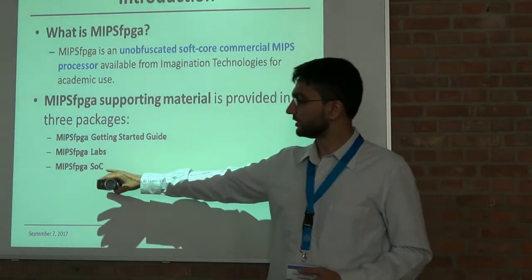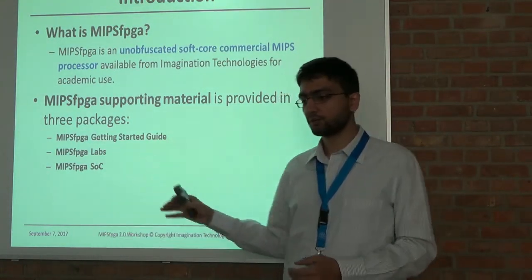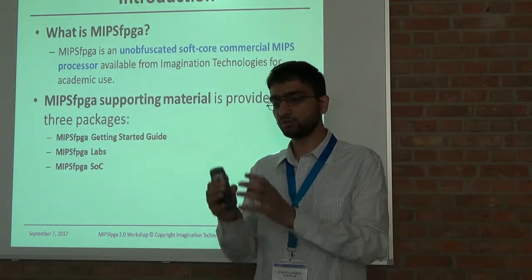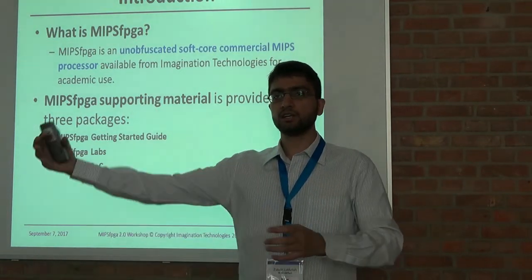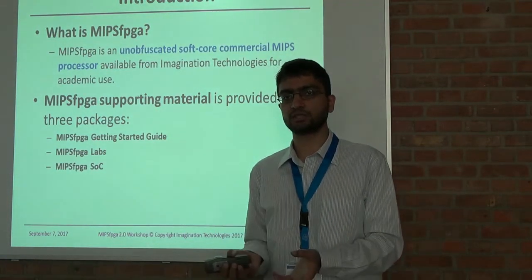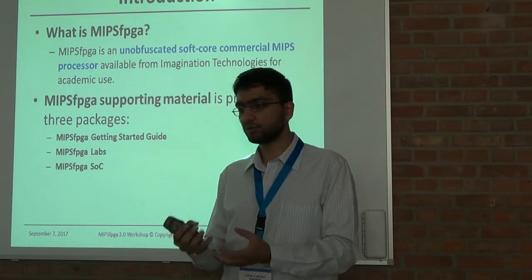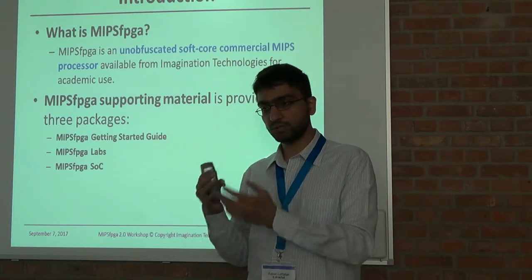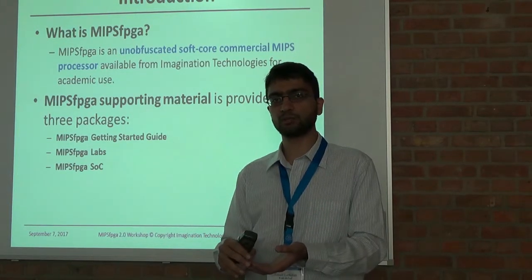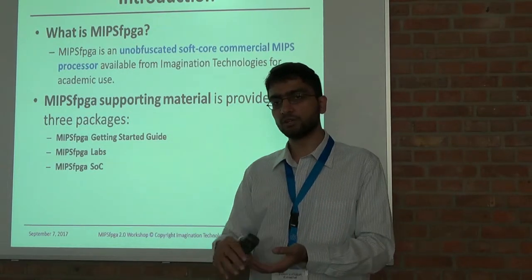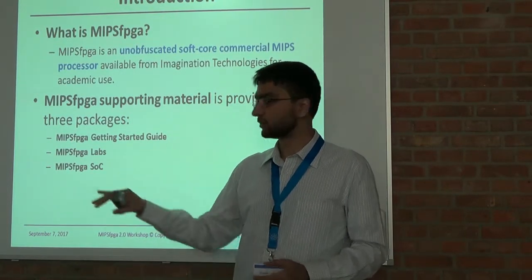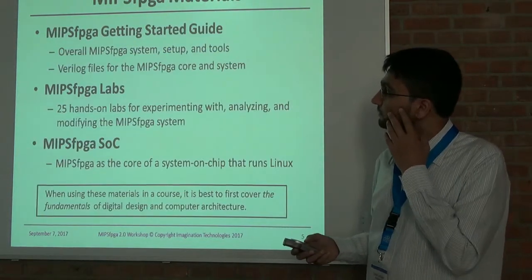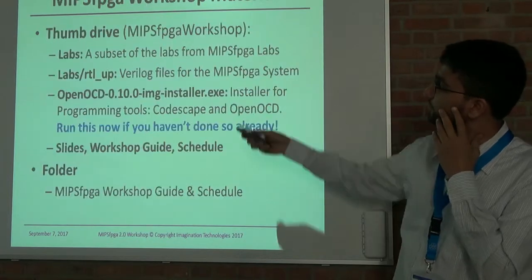So the third package is MIPSfpga SoC. Now, this doesn't go inside the core, but covers all the things around it. How do you use a MIPS core in industry, use other IP cores to build an SoC around it, and how do you build an SoC which is capable of running Linux at the end? How do you then port Linux onto your new hardware platform on FPGA, and how do you build embedded Linux on top of it? So that's the third part in terms of SoC, so how you can run Linux on MIPSfpga.